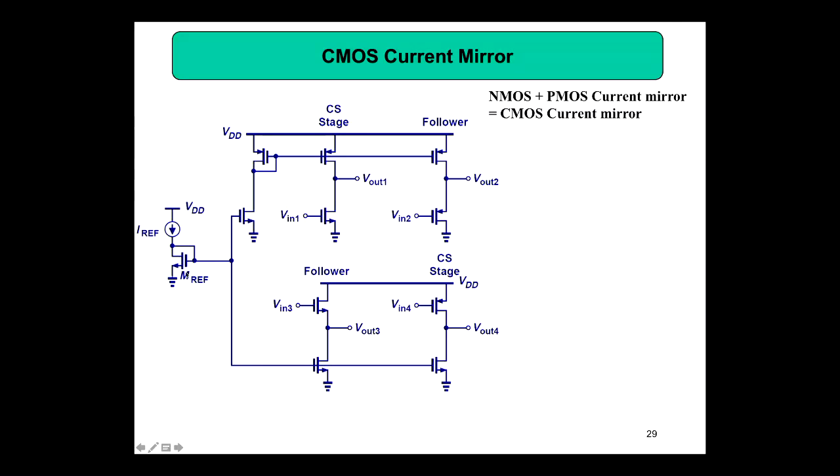So that's how. When you have a big circuit, I will show you in the coming lecture, you can actually find out what is the current flowing through maybe one amplifier stage. It is just simply some maths, because you know how this will be mirroring, and if this is 0.2 milliamps, you can find out what is the current here in each branch, and then we can exactly tell what is the current maybe flowing through this circuit, or maybe this part. We can actually find out. This is very simple to write. I will show you some examples in the next lectures.